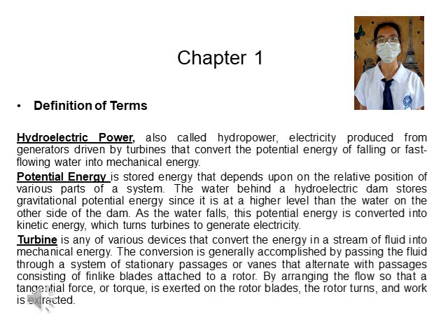Turbine is any of various devices that convert the energy in a stream of fluid into mechanical energy. The conversion is generally accomplished by passing the fluid through a system of stationary passages, or vanes, that alternate with passages consisting of fin-like blades attached to a rotor, by arranging the flow so that a tangential force or torque is exerted on the rotor blades. The rotor turns and work is extracted.